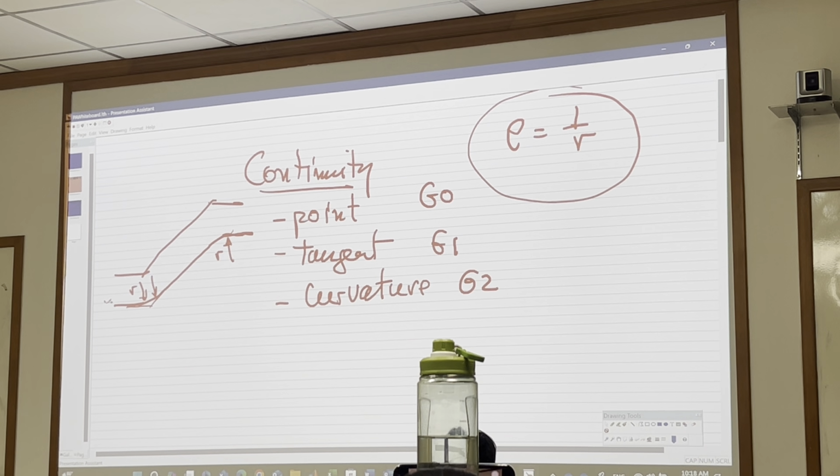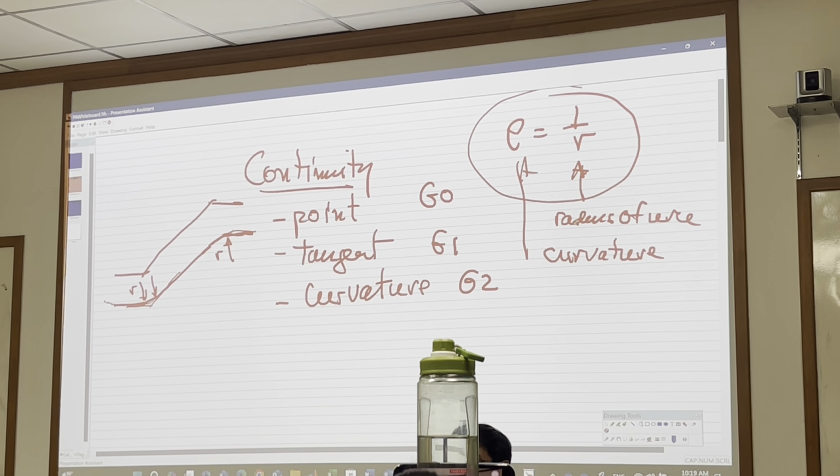The r converting from this one to this one is very smooth. The surface is much smoother. Because r is the radius of curve, right? Rho is curvature, right? Curvature is equal to 1 over r. Either one can be displayed anyway. It's equal. Sometimes we normally use rho, curvature continuity.